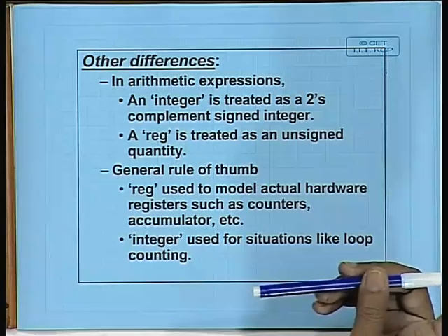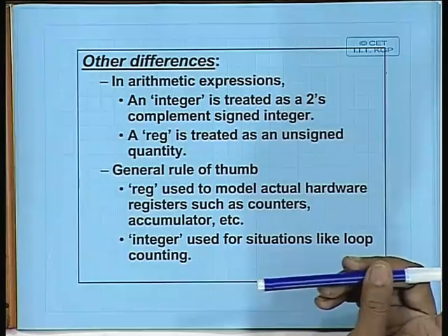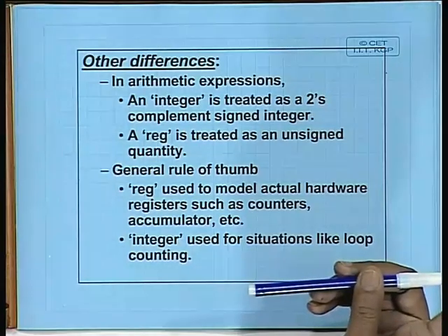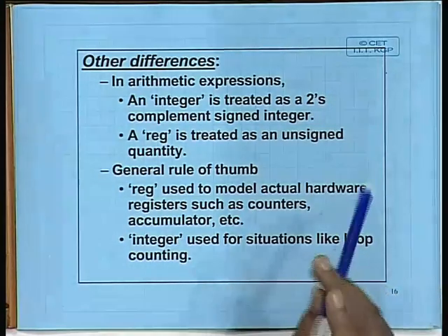So the input output connections, are they regs or nets? Input output connections are neither reg nor net, they are just some signals coming in. Their type will depend on the driver module, the module which is driving those signals. So whether they are driven from a reg type or a net.